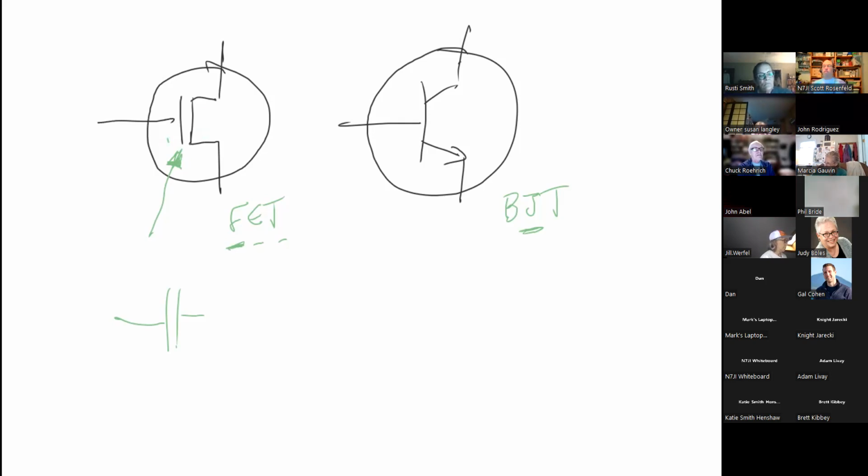So by altering the voltage instead of the current, what we've done is we have generated a device that creates a copy in current of a voltage. And because there is no leakage across this junction right here, because it's a capacitor, it uses very, very low power, especially when there are, let's say, 1 billion of them on a chip, which you'll find in your phone.